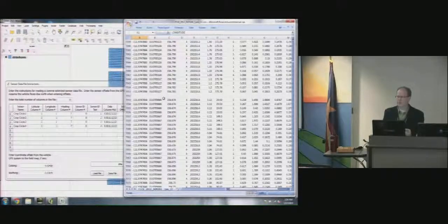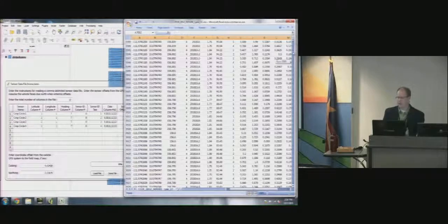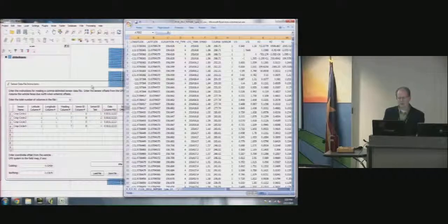So just for whatever reason, the way that this file was written out, it has this characteristic that there's a missing line. And so in order to handle that case, the way that I'm handling it is to say that the user has to tell the GIS how many columns are expected, and then the software will ignore any lines that have different numbers of columns.